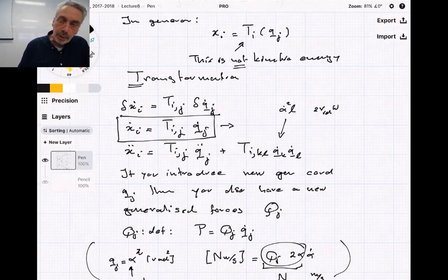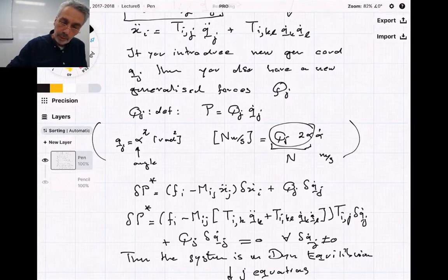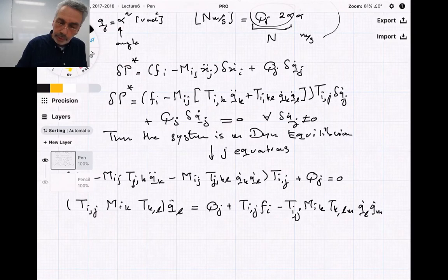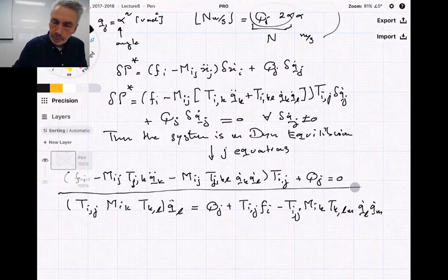So we started, of course, with our functions, with cosines and sines and the CM positions, and then we take the derivative, and then we get a nice matrix. In our case, for the pendulum, it will be 6 by 2, and then it's just the transformation matrix of the velocities, in fact, and also the forces. Okay, so finally, this is our nice equation of motion.